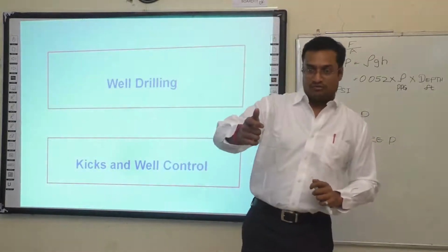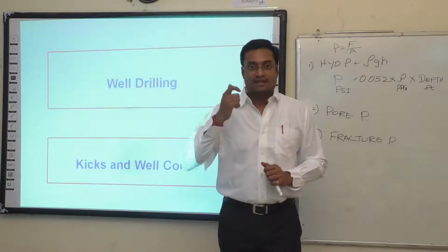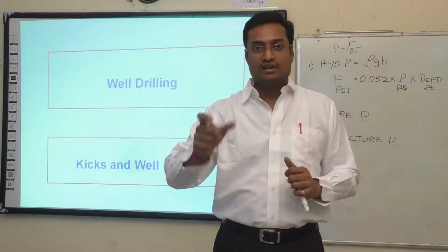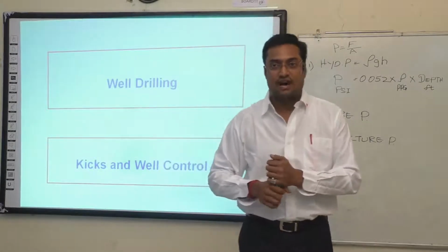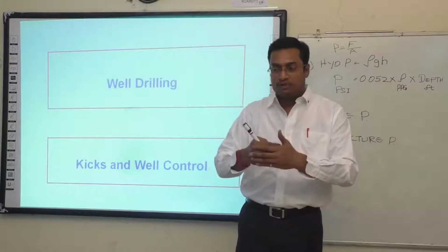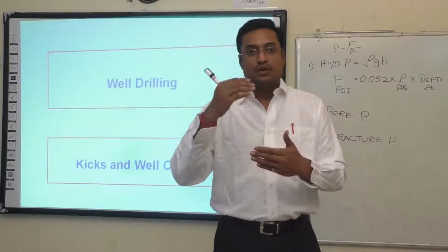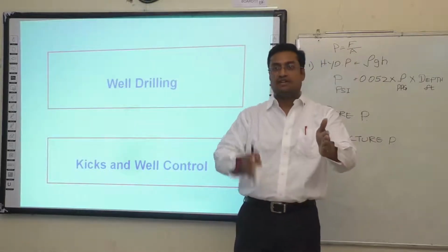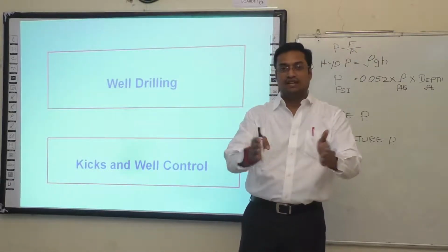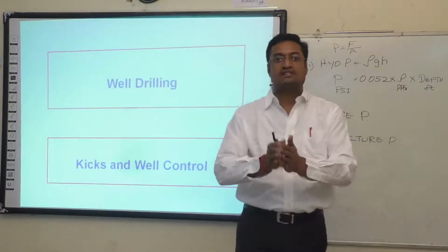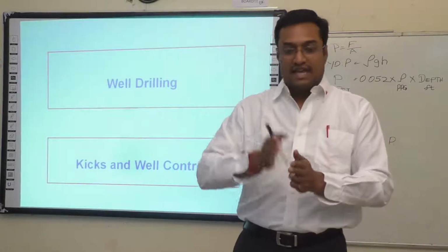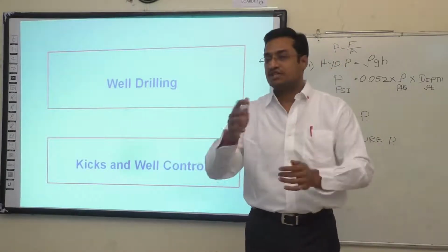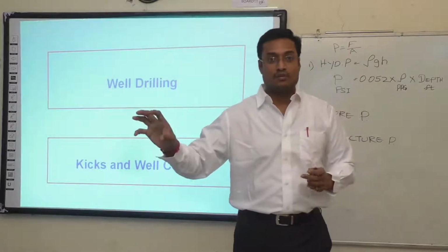So what is well control? Again, the pressure differences inside the wellbore causing problems, or in other words, the problems which are caused due to the pressure differences inside the wellbore between the hydrostatic pressure and the pore pressure. Those problems we call well control problems. If it is any other problem out of these pressure differences, we call it well problems.